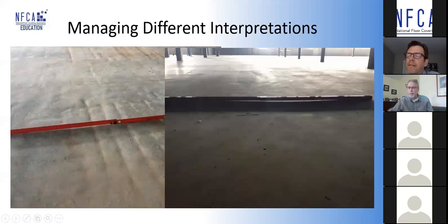Keith, I think it's important to qualify smooth. Exactly what is smooth trying to say? For the floor coverer, it's directly relative to CSP, which is texture in the surface. CSP is concrete surface profile, and it actually needs to have a little bit of grit to it, like fine sandpaper. So you can have that sort of chattery look on the left and it still be smooth from a floor covering perspective, apart from little lumps. Very smooth would be 100 grit sandpaper or 1,000 grit sandpaper. Less smooth would be 60 grit or 40 grit sandpaper. That's what it's trying to point out for us. And that's so we can get mechanical on it.